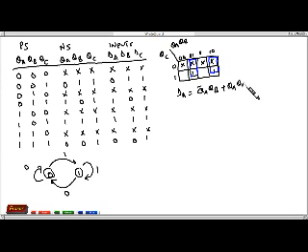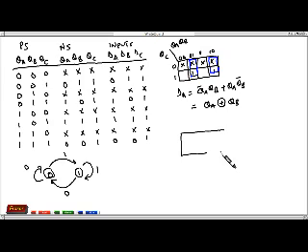If you look at this, it is the XOR expression, which can be written as QA XOR QB. And that's our DA. For our DB, we use again a 3 input K-map.